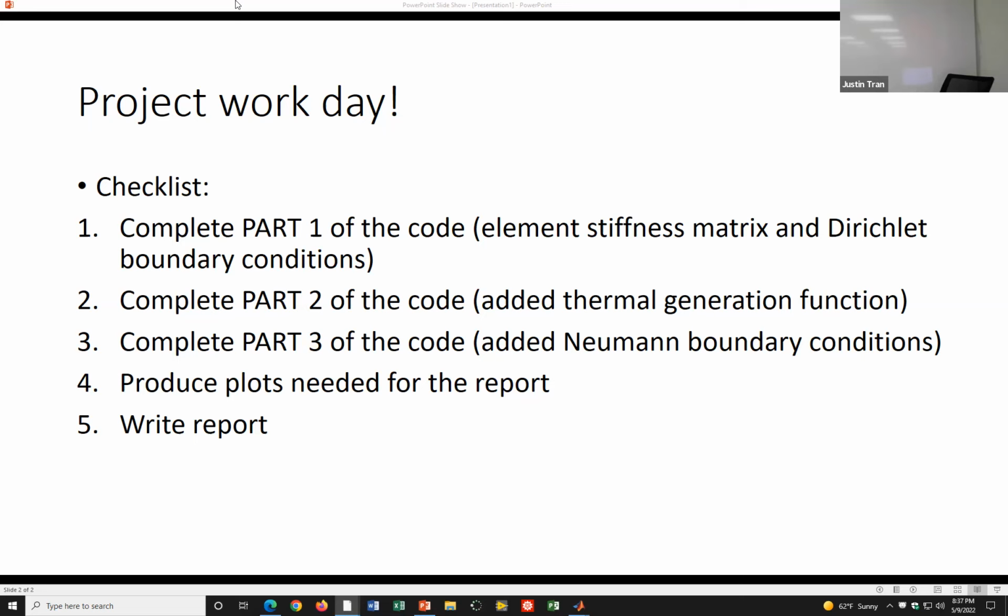There's some randomness. When you generate the mesh, we're using basically a mesher inside MATLAB. Even if you have the same element size here, it's going to produce slightly different meshes, just because of the way meshing works. It depends on some of the random values inside the computer. The way meshing works is that I don't have a figure, but basically it takes your domain and puts points in semi-random places. All the nodes are in semi-random places, and then it connects them in semi-random ways too. And that's computer specific.